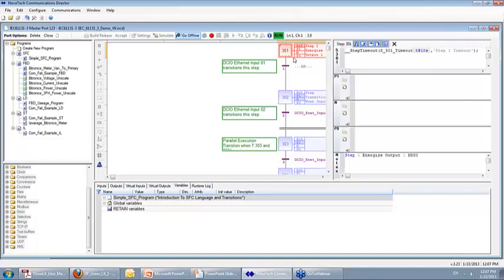Within the programming environment, I can write various scripts in ladder diagram, function block diagram, instruction list, which will execute either when an initialization and entering the block occurs, on the rising edge of program entry, continuously every time the step is in that stage, or whenever the execution of that step transitions from one step to another.